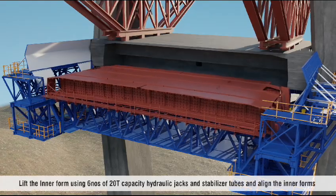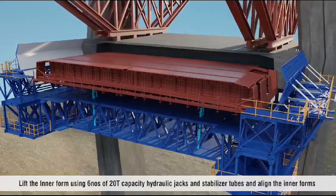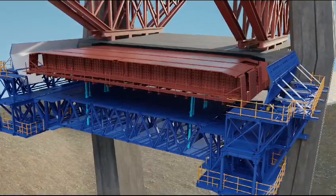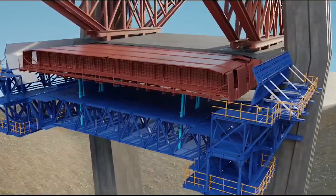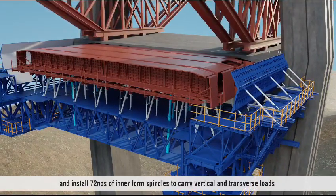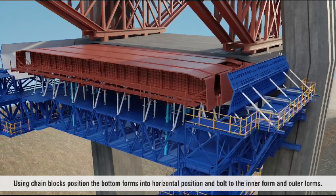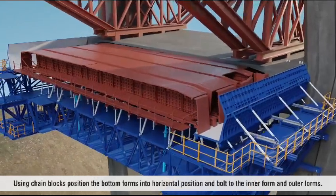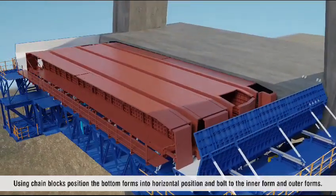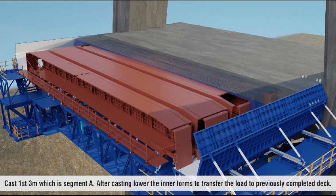Lift the inner form using 6 numbers of 20-ton capacity hydraulic jacks and stabilizer tubes and align the inner forms and install 72 numbers of inner form spindles to carry vertical and transverse loads during casting operations of segment A, B and C. Using chain blocks, position the bottom forms into horizontal position and bolt to the inner form and outer forms. Cast first 3 meters, which is segment A.